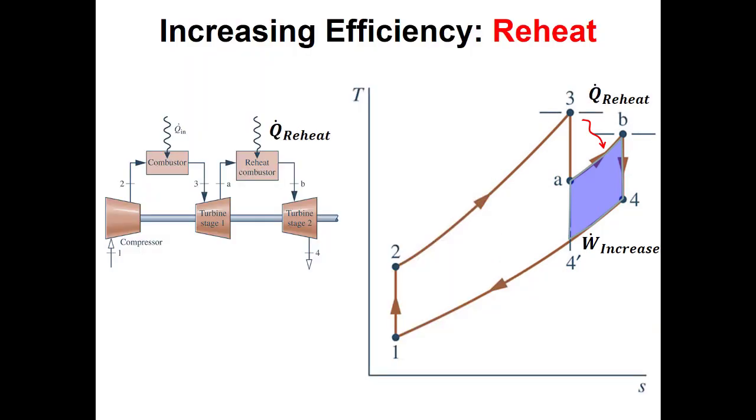And we know for these isentropic or ideal cycles that the area inside this TS diagram is the net heat, and the net heat would be equal to the net work. So what happens here is we added this little extra area, which I've circled and colored in this sort of transparent blue. So that means that we've added more work. And what happens is we increase the work in a way that increases the thermal efficiency, right? So the net work is going up in a way that the efficiency gets higher.